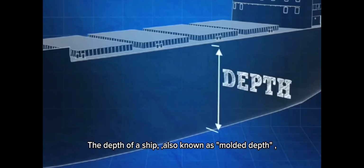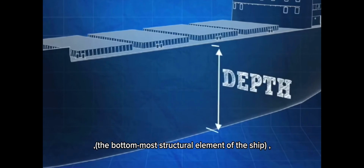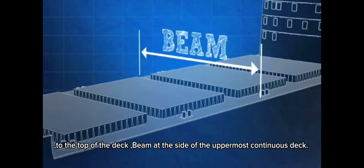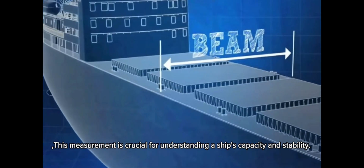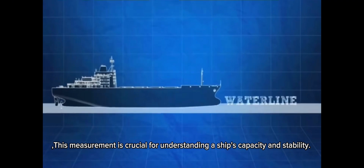The depth of a ship, also known as molded depth, is the vertical distance measured from the top of the keel, the bottommost structural element of the ship, to the top of the deck beam at the side of the uppermost continuous deck. This measurement is crucial for understanding a ship's capacity and stability.